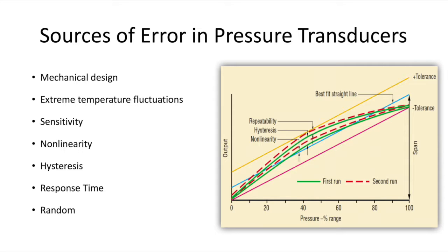Nonlinearity. The linearity of a transducer is an expression of the extent to which the actual measured curve of a sensor departs from the ideal curve. This error shows up as an exaggerated output when compared to the actual value. Linearity is often subject to environmental factors, including temperature, vibration, acoustic noise level, and humidity. Hysteresis. A transducer should be capable of following the changes of an input parameter regardless of which direction the change is made. If an error exists, there may be a discrepancy in measurement for increases or decreases in input data.